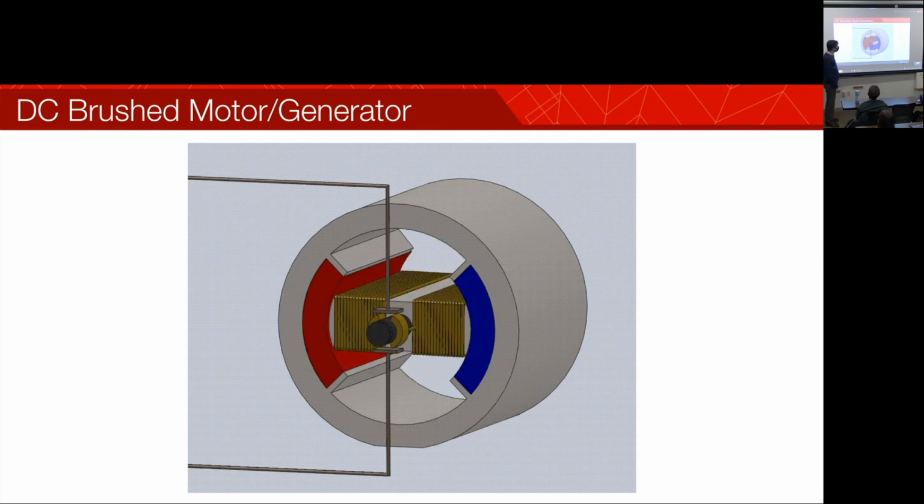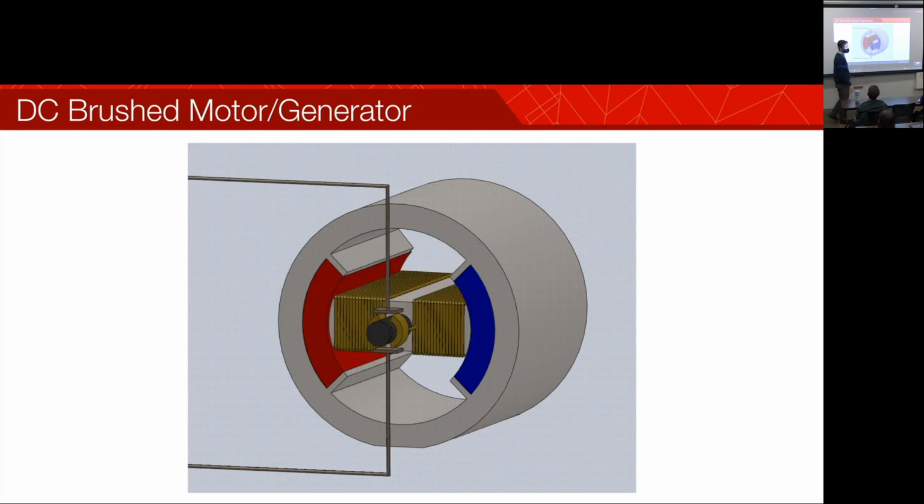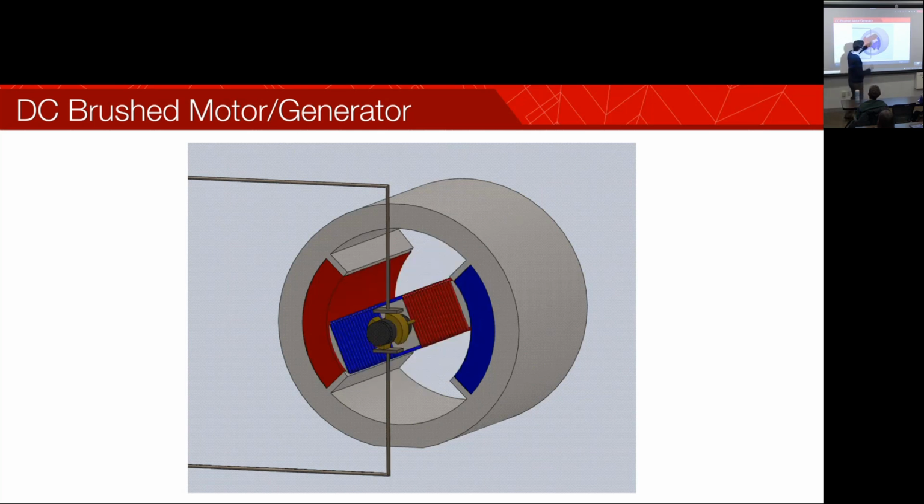What happens when it turns yellow? It's essentially in that split second you were just talking about, where the brushes are missing those shoes. Okay. But it's such a short period, and there's enough momentum, enough rotational inertia, that it can skip over that little bit. But the problem is if it happens to be right at that yellow point when you're trying to start your motor.